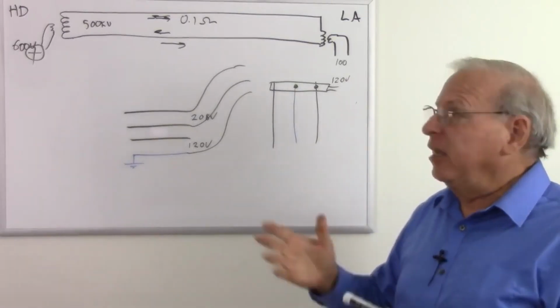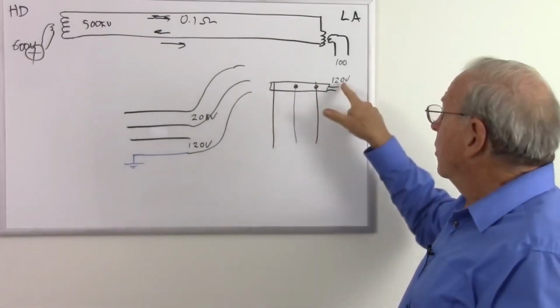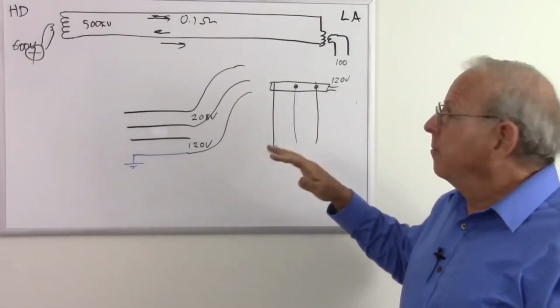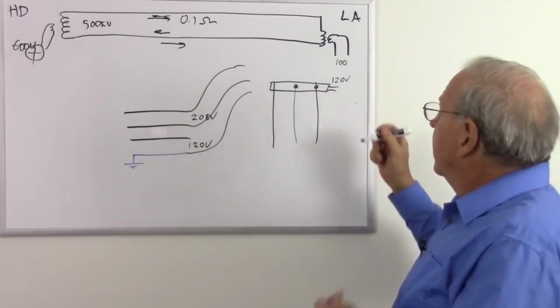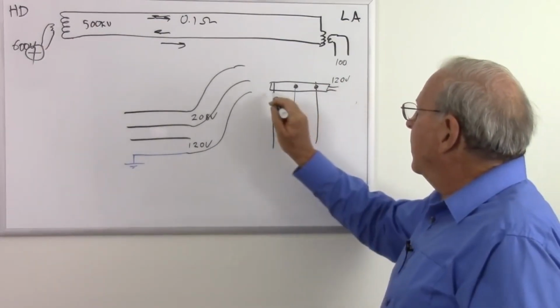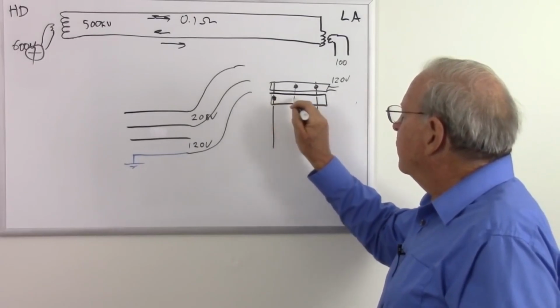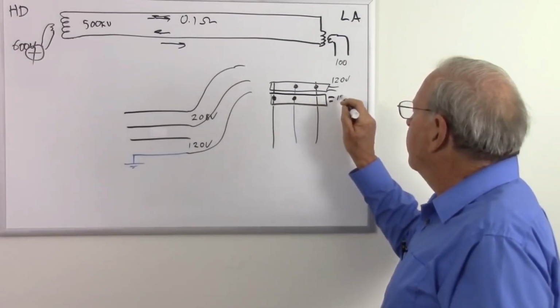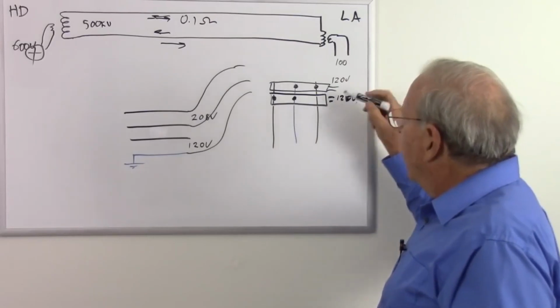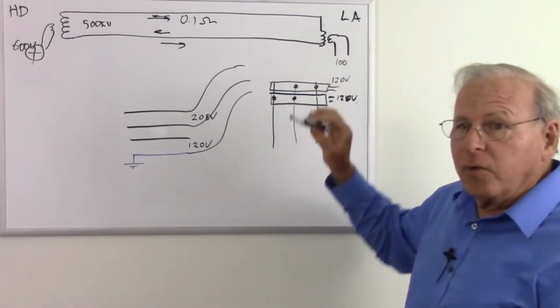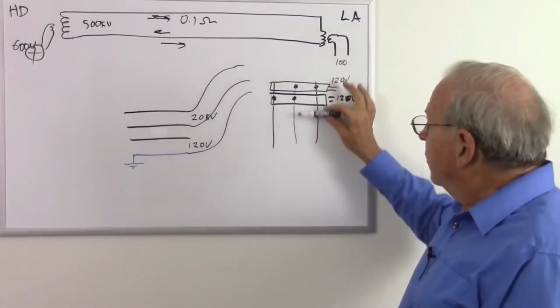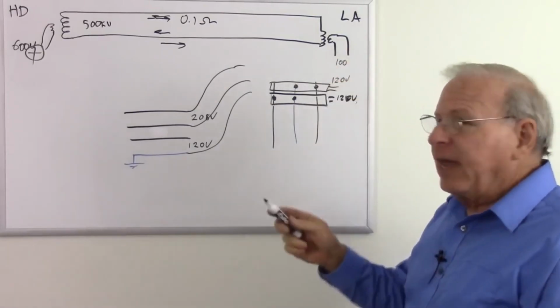Actually, I've seen in the Southern California area, it's more likely to be 117, but it just depends on where you are. 120 volts, and then let's say the next breaker connects to this phase and the neutral, giving you 120 volts. And they will alternate which circuits are on which phase and the neutral, and balance that out.